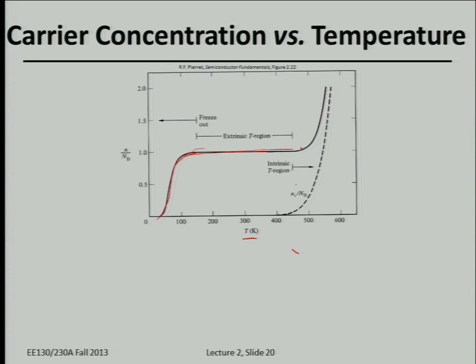The intrinsic carrier concentration, the electrons that have enough energy, 1.12 eV, to go from the covalent bond to become a free conduction electron, is very small. But once you heat up a semiconductor to very high temperature, there is more probability that electrons come directly out of covalent bonds, and the electron concentration starts to be dominated by the intrinsic concentration rather than the dopant concentration.